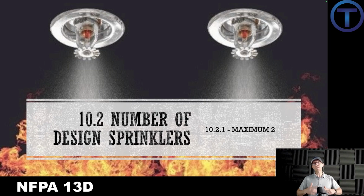Now, please keep in mind, we're dealing specifically with residential fire sprinkler systems. You can imagine a big warehouse where you see 20 heads in one space. Yeah, that's a different sizing in the NFPA 13, not the 13D. We're looking at a residential setting. We're looking at compartments or rooms that are not going to be enormous, and that's where coming right back to 10.2.1, 2 is going to be your maximum in any of those spaces. You'll have to place those heads in an appropriate way so that they're going to do the most good and avoid obstacles, as we looked in chapter 8. But 2 is the maximum number.